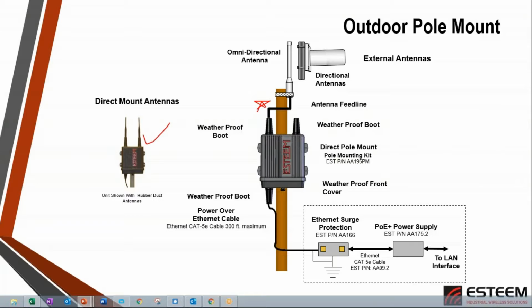So the 30-foot cable that we calculated was necessary for the 20-foot antenna heights. In a pole mount application, that cable is actually Ethernet. The beautiful part of that is that we can actually run that Ethernet cable anywhere up to 300 feet away from the equipment that it's actually being hooked into, and it has the same amount of loss as far as the radio is concerned. It will not affect how much energy is being put into the air, so it's a much more efficient way to do it.